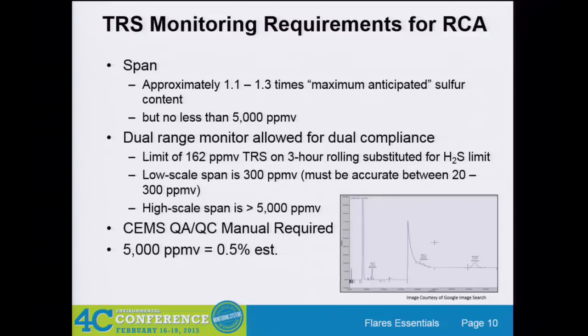So that's where we see a lot of facilities saying, especially if you're in that high range of, say, 50% H2S, that's going to determine some technology things. And so you're going to be moving towards a technology that can go all the way to 100%. And there aren't a ton of options in that. For a total sulfur monitor, you're looking at most likely a Thermo Scientific Sola 2. Those ones can go up to 100% sulfur, with dilution.